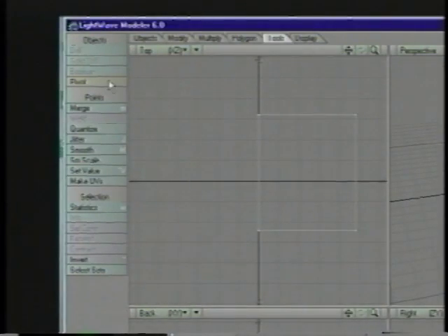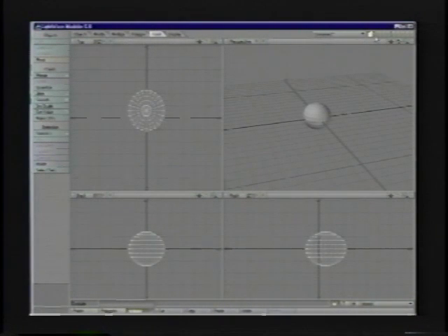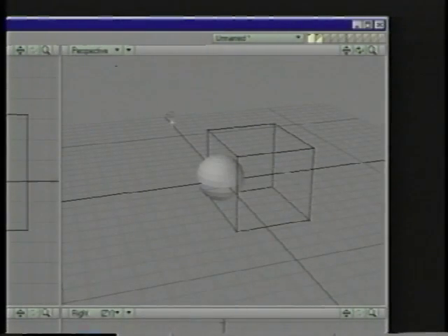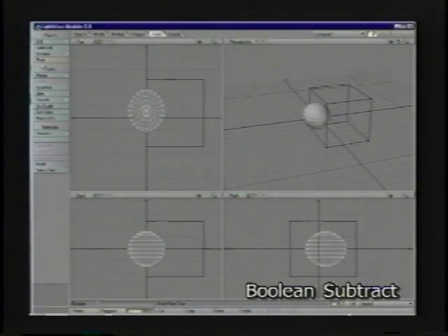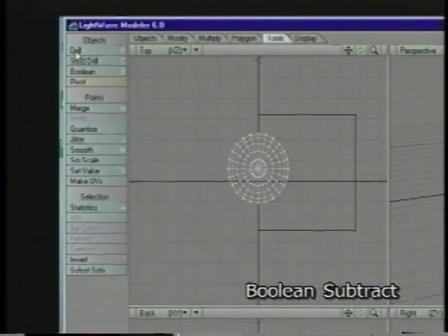And you can see we have, under Objects, ghosted out right now, our drill, solid drill, and Boolean. They're ghosted out because I only have a foreground layer selected. And as soon as I go in and select the ball as layer 1 and the box as layer 2, they become available. Now the first thing I want to start with is the actual Boolean tool. I'll get back to drill and solid drill in a minute.